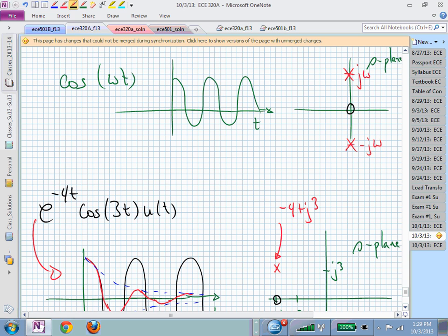There's no exponential decay. If you move those poles into the right half plane, what would the exponential look like? E to the plus 4t. Then it's blowing up with time, and I can't shake that way. I don't want to shake that way, right? Because in a little bit of time, you would be gone, unbounded, right? You don't want to see that. Would not be pretty.